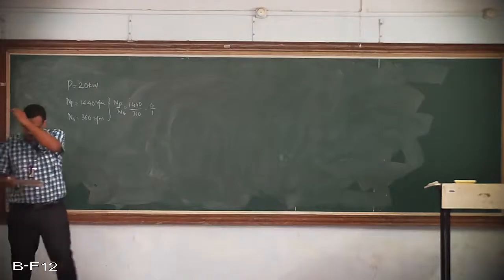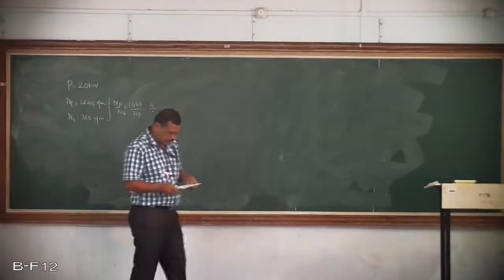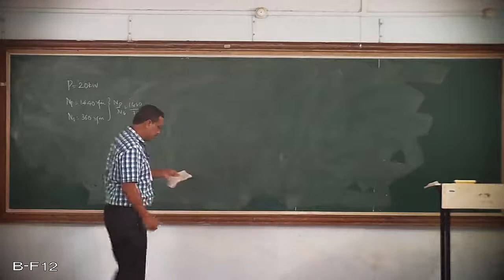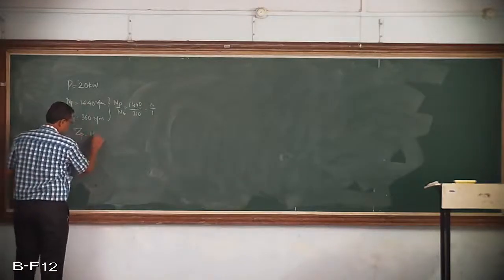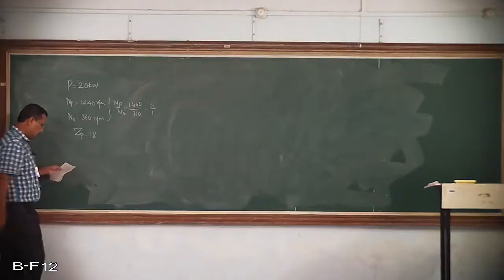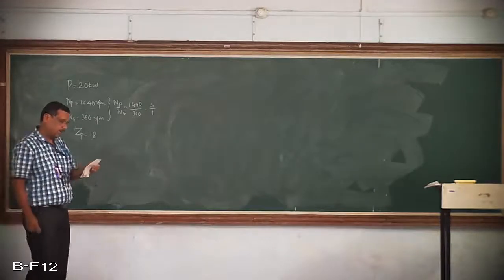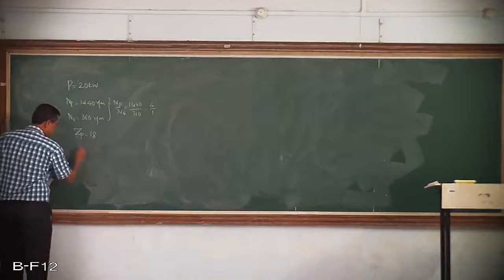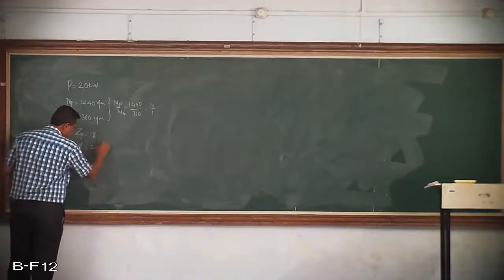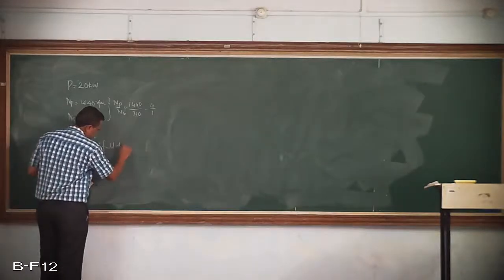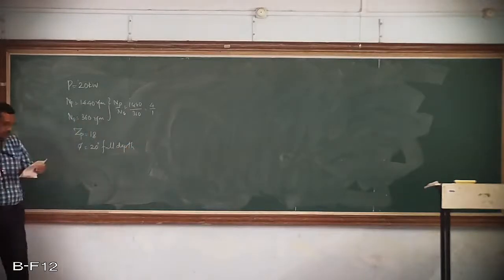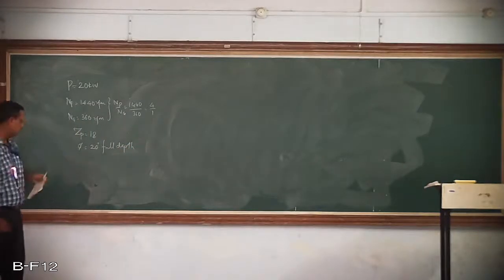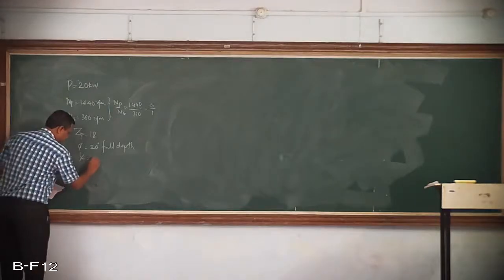The motor shaft pinion has 18 teeth. Therefore, the number of teeth on the pinion is given as 18. Now, the type of the teeth is 20 degrees full depth, so the pressure angle is 20 degrees full depth teeth. Then the helix angle, since they are helical gears, is given as 30 degrees.